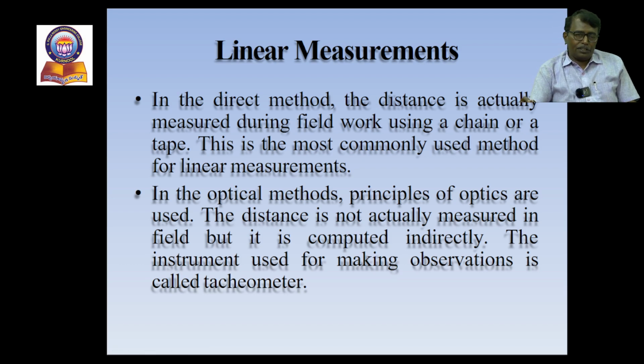Coming to the second method, that is the direct method. In the direct method, the distance is actually measured during field work using a chain or tape. This is the most commonly used method for linear measurement. We will discuss the direct method in detail in the coming slides.